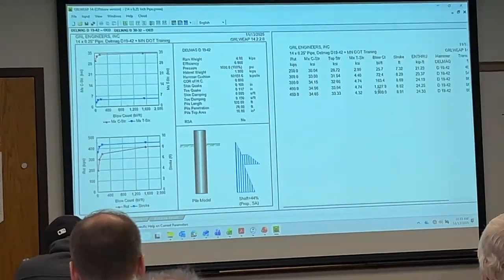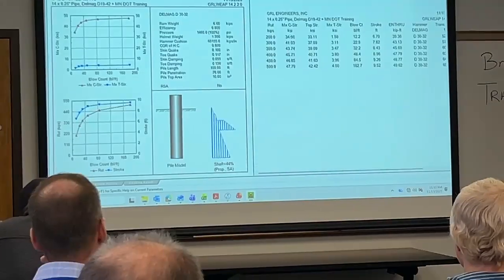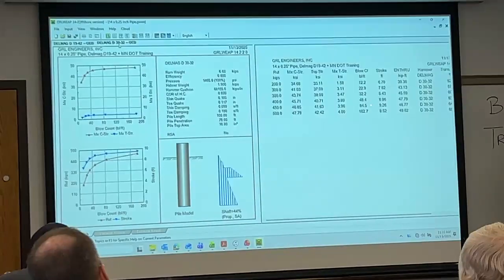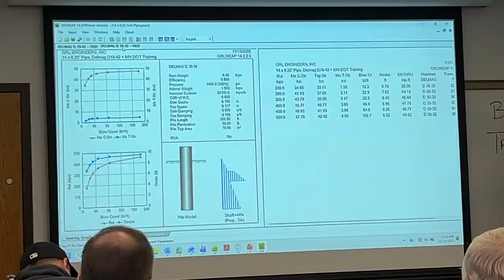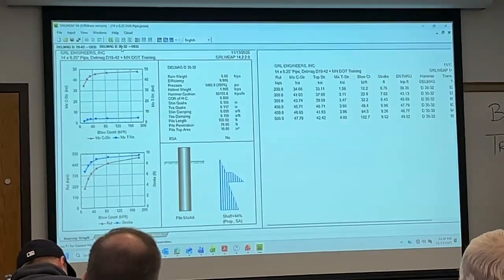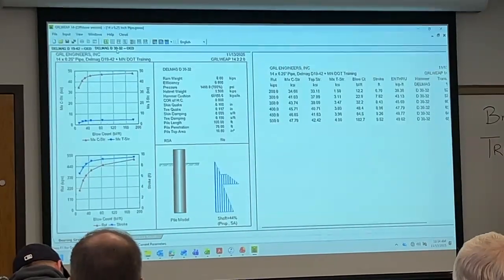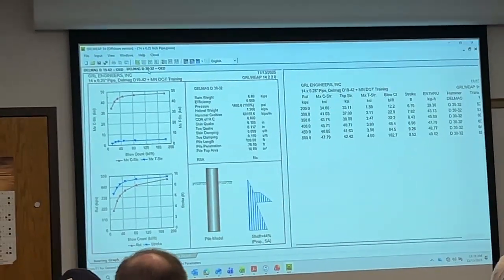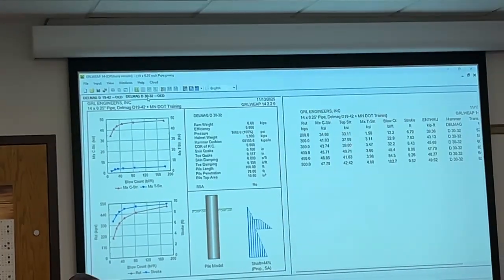So here's the D19 results you saw. We cannot achieve the 400 kips. D30. Okay, our blow count is 50 blows a foot, so this is looking pretty good. Except now our stresses are in excess of the driving stress limit. So, like I said, I'm assuming you're gonna have grade 3 pipe with a yield strength of 45 KSI. Specs limit driving stress to 90% of that for a steel pile. So we need to show that this can get within 40.5 KSI.